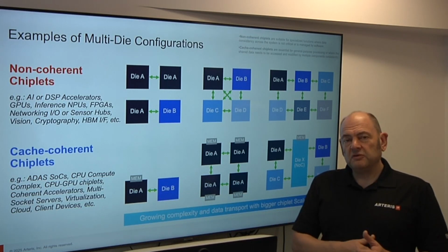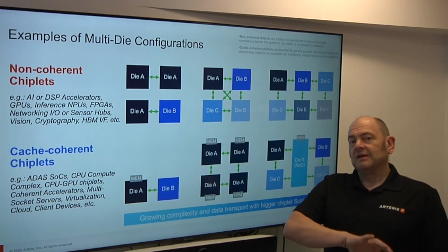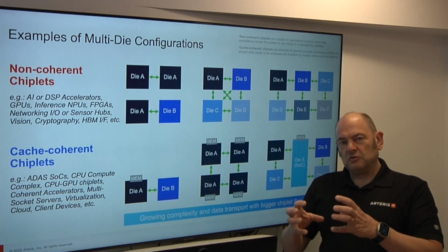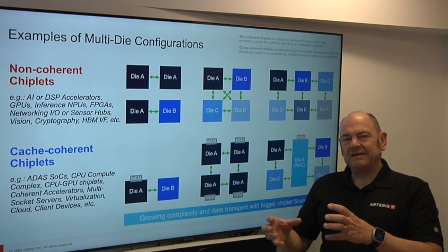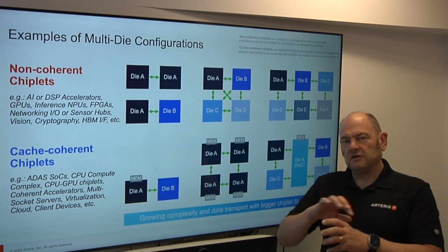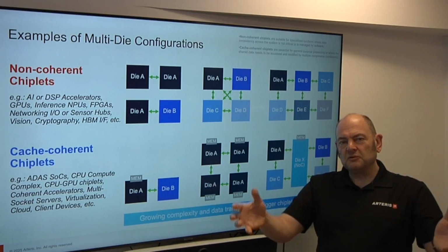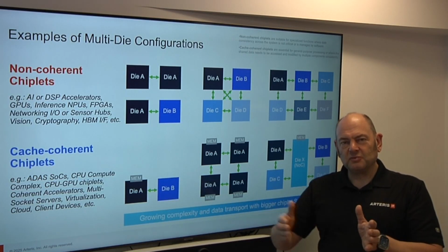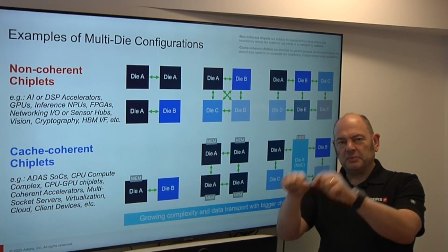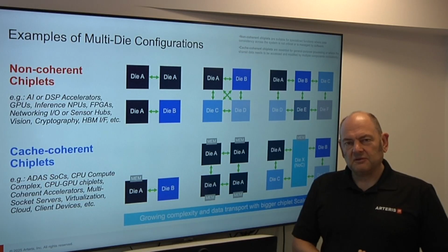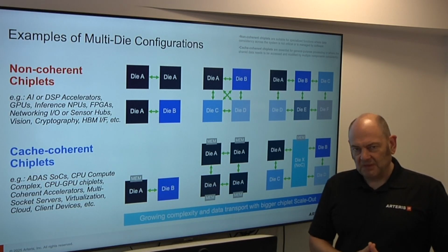So for multi-die designs with new chiplets, the derivative is you can actually replace that new hardware in the next spin by just replacing one of these dies and keeping the rest of the system the same. Again, analogous to keeping your PC motherboard the same with all its other peripherals and cards, and swapping in and out the graphics card. So time to market is radically reduced.